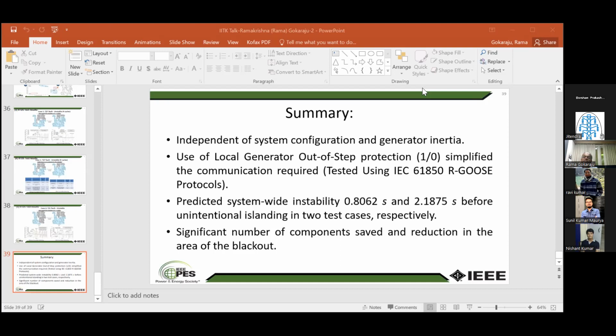What I'm saying is that was real time, based on the PMU measurements. After a fault event happened, how those generators are splitting, monitoring those angles at the various buses, that's how I'm showing the coherent groups. Okay, sir. So you're doing that in real time. Yeah, real time.